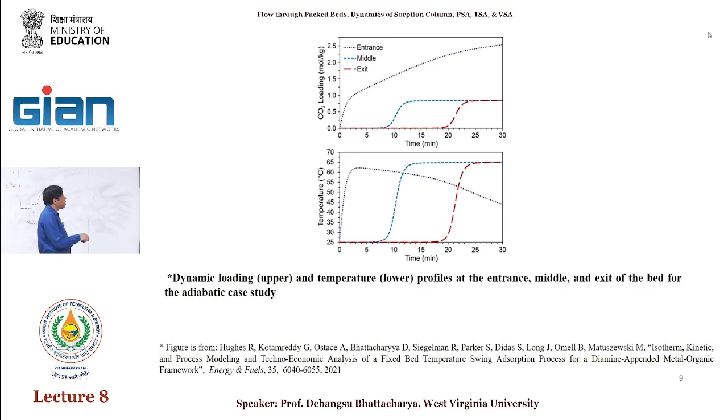The reason is that the temperature is going up. This is the issue with the fixed bed: the moment it captures, heat is released and the temperature immediately shoots up, which affects your isotherm. When Dr. Pala discusses this today, and I know yesterday you had some discussion about the isotherm, you will see that higher temperature does not favor equilibrium and hurts you in terms of loading. That's why you can never capture this fully. You notice they go to the same loading because they go to the same temperature.